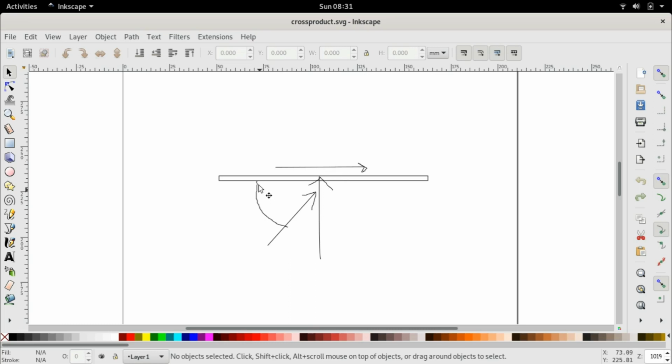So you see here we had already seen that when the magnetic field is at 90 degrees to the current, the mechanical force produced is maximum. When the magnetic field is at an angle which is less than or greater than 90 degrees with respect to the current, in that case we take the sine of the angle to determine the projection of the magnetic field which is at 90 degrees to the current.